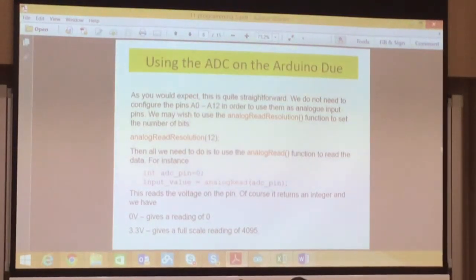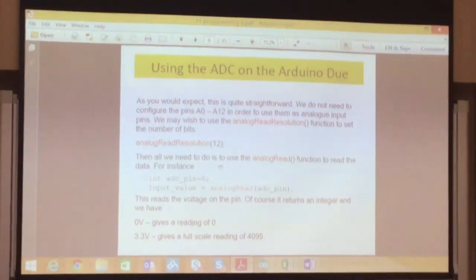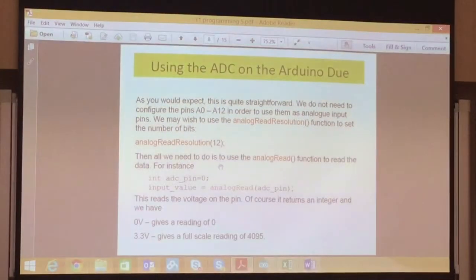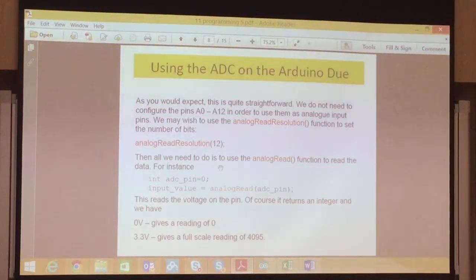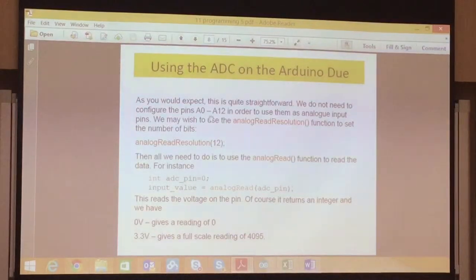But if you define your analog resolution to be 12-bit, how many possible values do you have? It will be 0 to 2 to the power of 12, minus 1. So you will have 4096 possible values. Okay. So that's one thing you have to define for the analog reading. And for the Arduino board, in the lab, you always use the digital I/O. You remember, you take one of the pins from the digital I/O. Actually, on the other side of the Arduino board, let me show you.